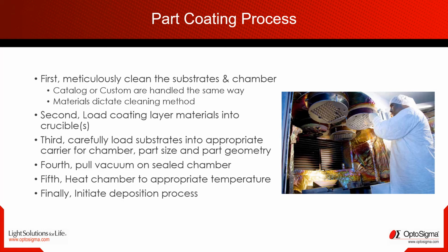When the chamber is sealed and placed under vacuum, unwanted materials can outgas and contaminate the parts and chamber. And if the vacuum pumps are not properly maintained, they can leak oil or not properly maintain the necessary vacuum during the coating process, and it can again cause failure of the coating.